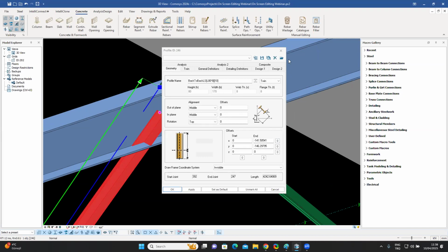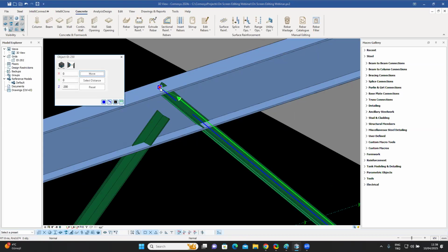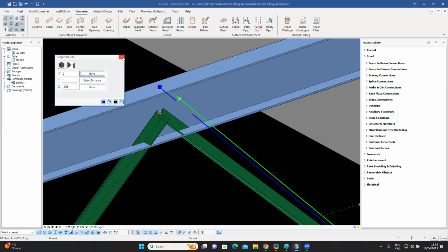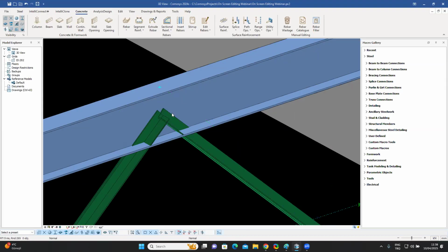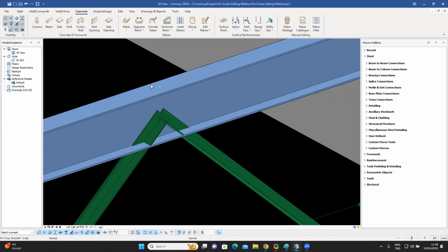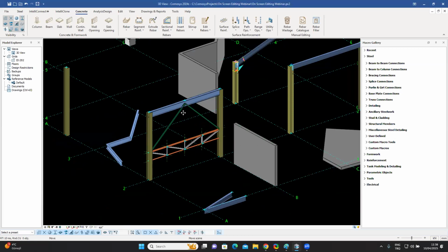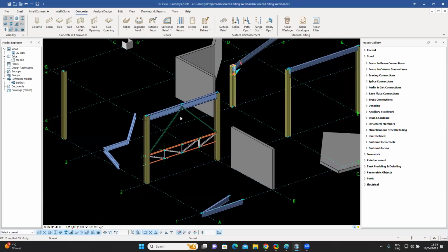You can do them like this as well, but it's much easier, for example, to select this one, then go in and select the adjust button handle over there and say move. And now both the vertical bracing have been moved to that point while my finite element model has been maintained. So this is a very useful way of moving around the offsets of your frame elements.